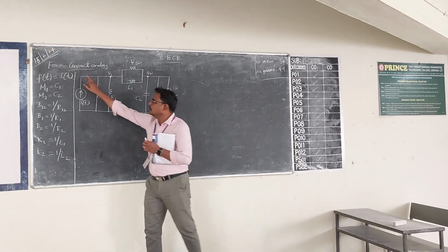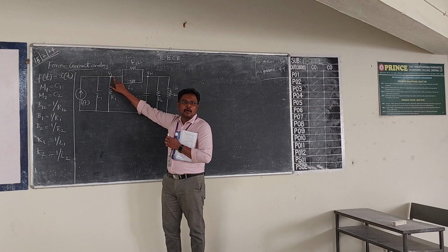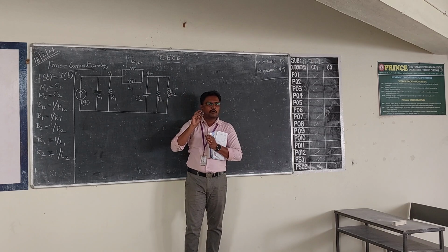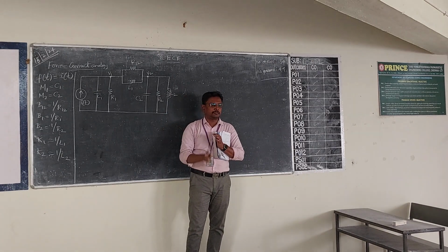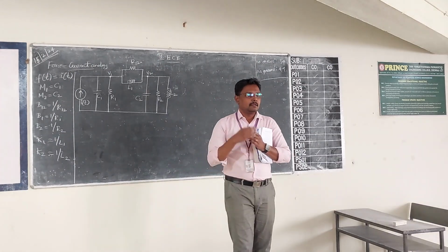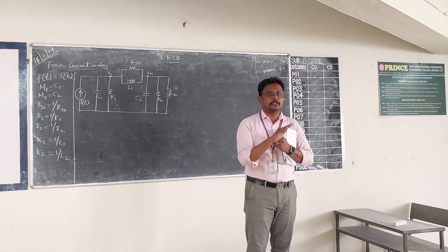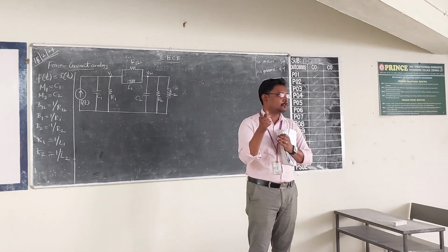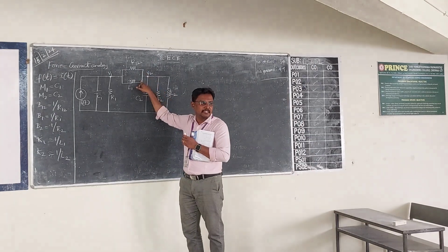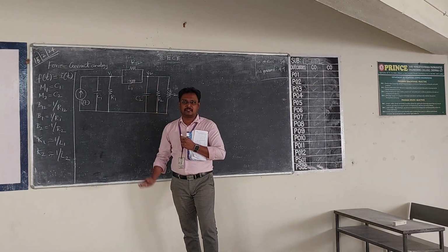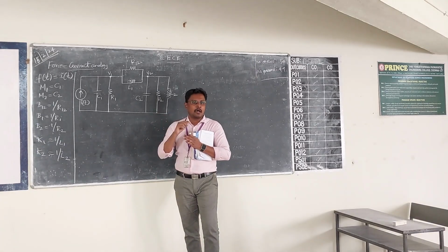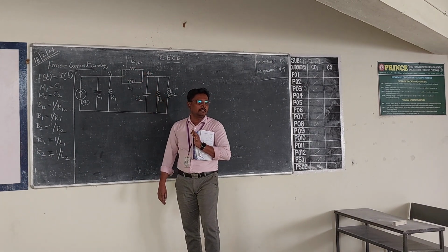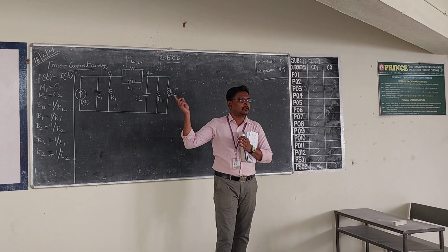Yeah, you are using the force current analogy. See what is this V1, V2? V1 is the first node, V2 is the second node. So you are placing the common elements between these two nodes. In mesh analysis, it was common between two loops or two meshes. Look at yesterday's diagram: mesh 1 and mesh 2, these two elements were in series and common between two meshes. Here, it is common between two nodes but these two are in parallel because you are using the force current analogy method.